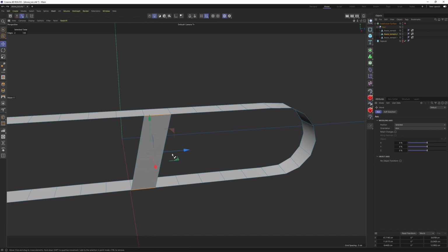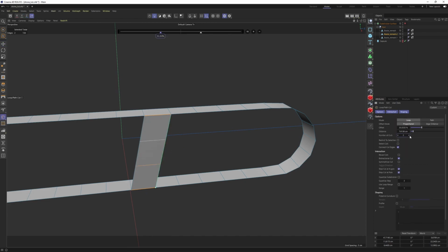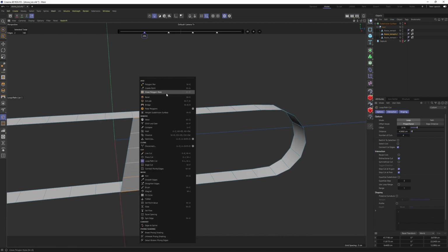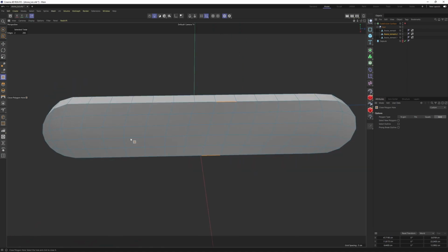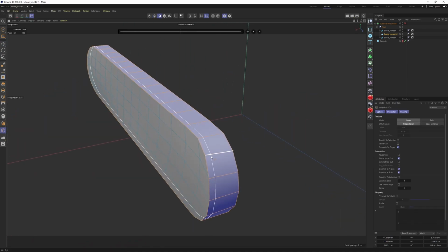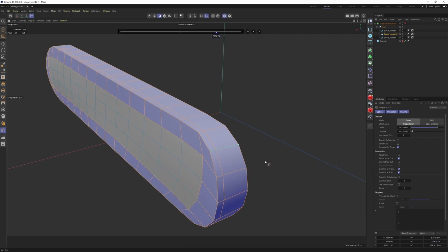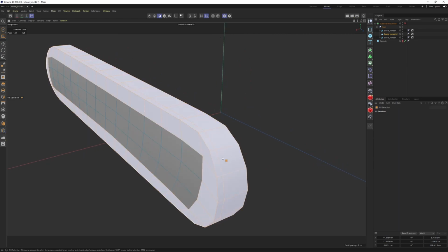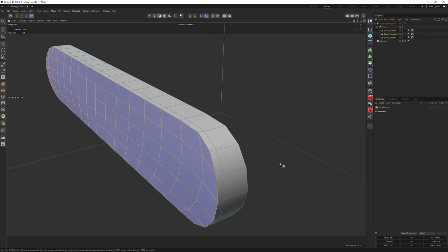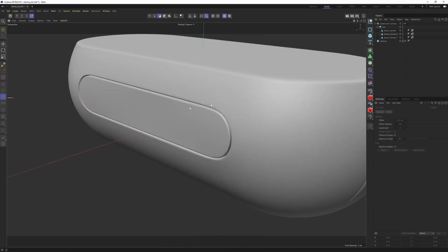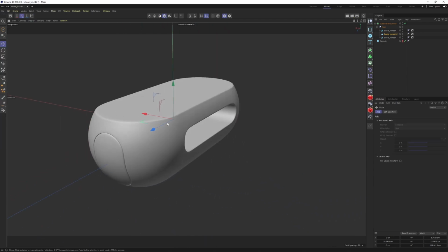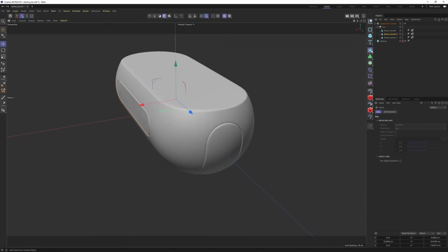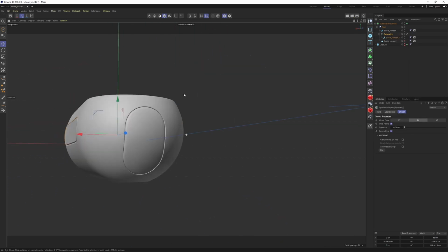I mean, let's make it something higher than 3, like 4. I'm going to try it one more time with the close polygon hole tool, and it worked perfect. And the other side as well. And it's loop cuts, then invert selection. No, loop selection, fill selection, make edge sets. Perfect. Of course, we want this to be on the other side. So hold down Alt, it is symmetry, and here we go.